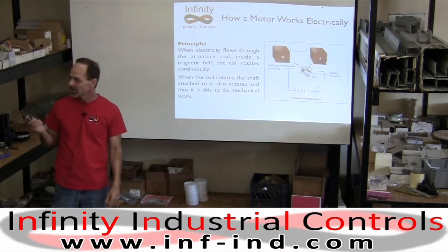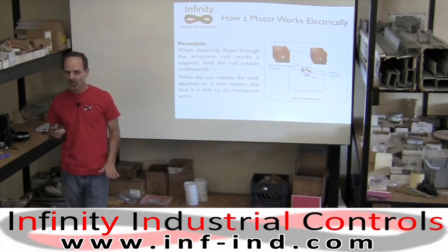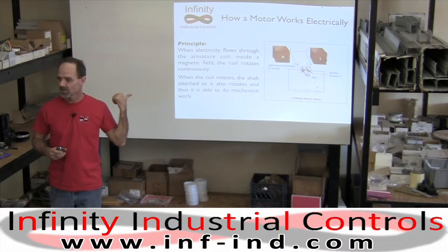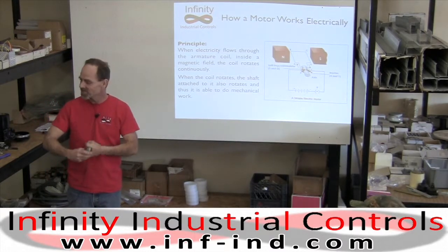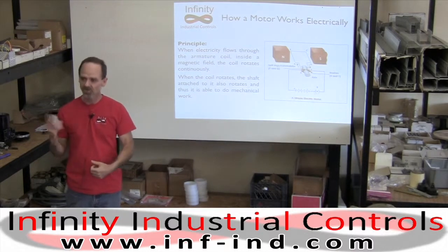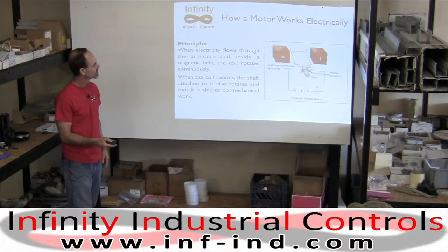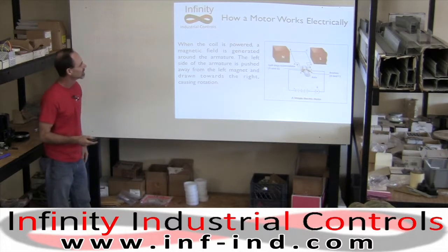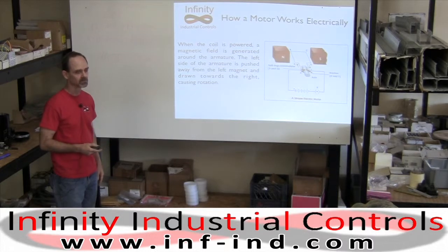She's got one of those little Prius cars. When you brake, if you brake too hard, they're going to engage the brake. But if you brake lightly, they're actually using the electric motor in there as a generator. It's changing mechanical energy back to electrical energy, so it's storing it in the battery. So as you brake, you get to save up some of your power instead of wasting it as heat. You hear the term regenerative drive on DC drives.